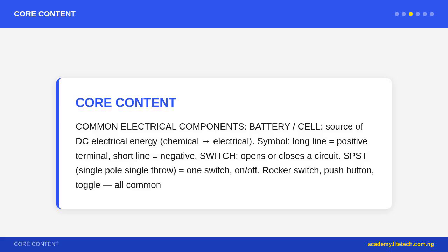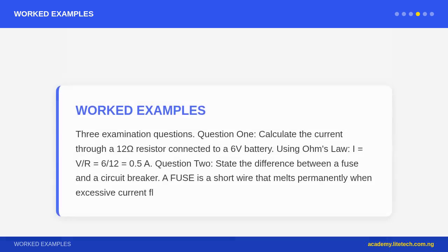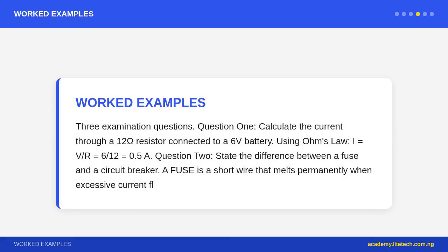Symbol: two-coil windings. Electrical safety in practical work. Never work on a live circuit; always switch off and disconnect the supply before making connections. Test with a meter before touching; use a multimeter to verify that a circuit is dead.